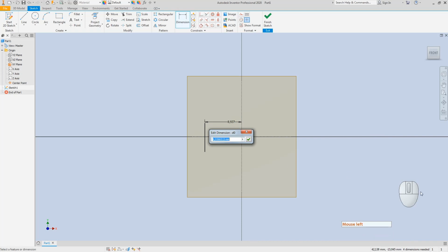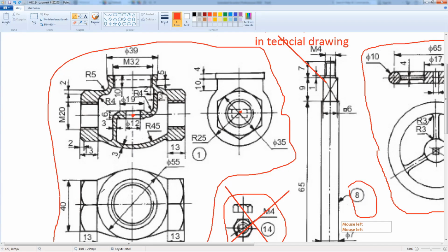I will just create two lines. I'm just going to make these lines for construction purposes. I would like to only mark where I am. For this reason, I will take the midpoints and stick to the origin point, which you can also use from this point.